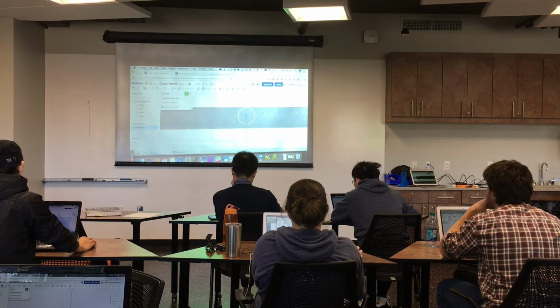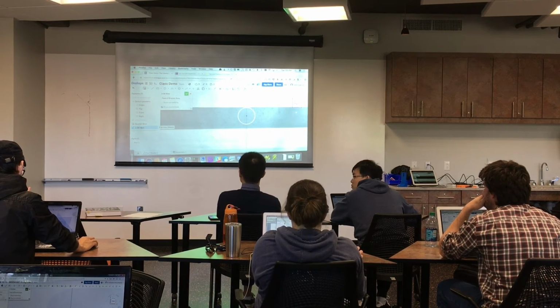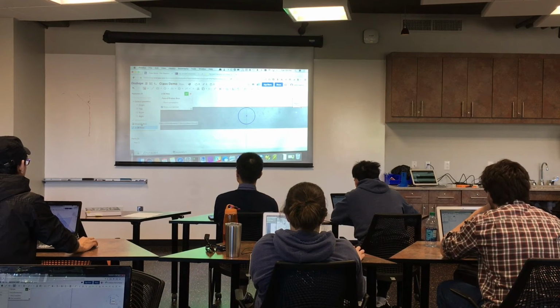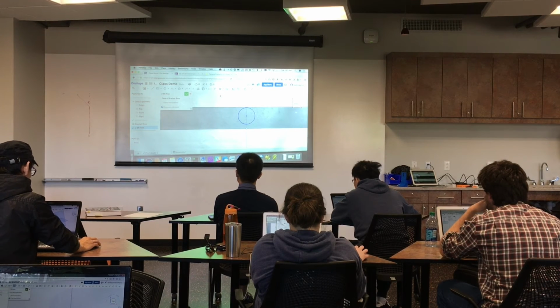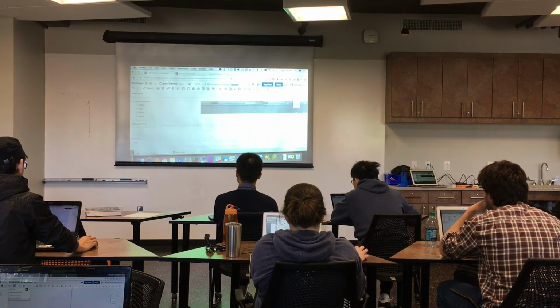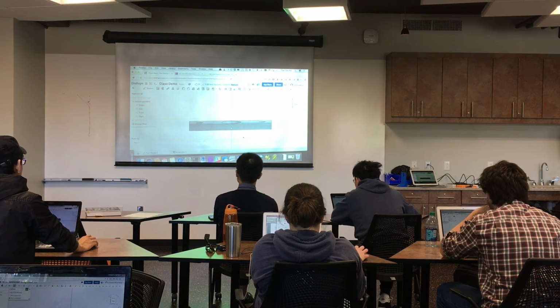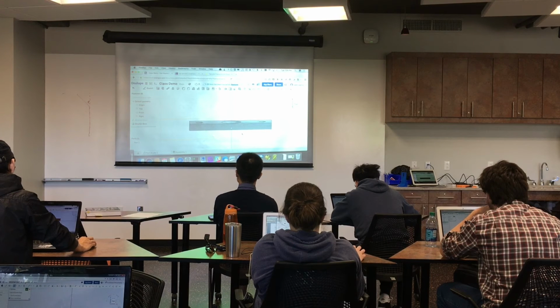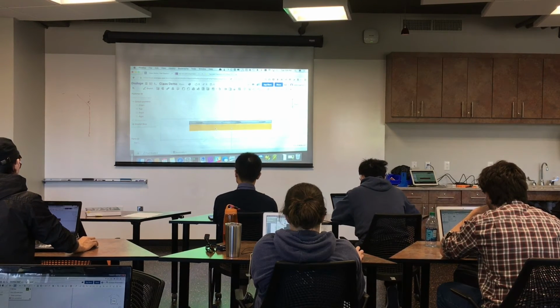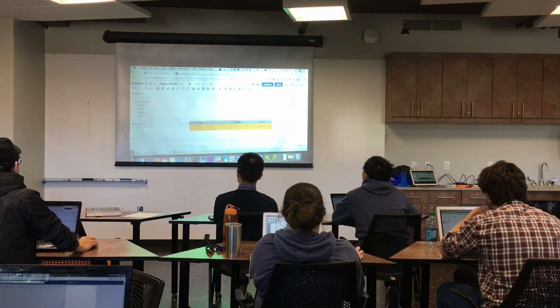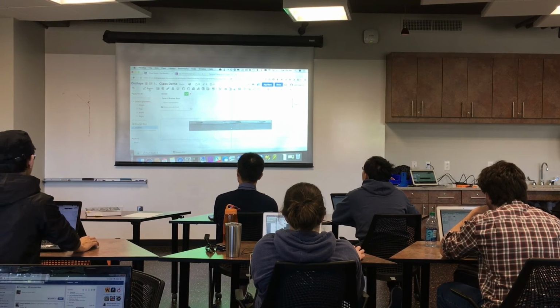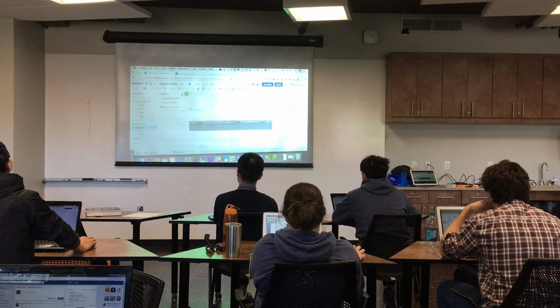John, I'll ask you. How'd you get this? How did I get what? How did you get from the last place that we were at to here? Ah, okay, yeah. So let me delete this and I will show you again. So you're here, right? All right. So you select the face that we want to do the sketch on. So like we would click on this front face so that it's orange. Okay. And then click sketch. And name it.